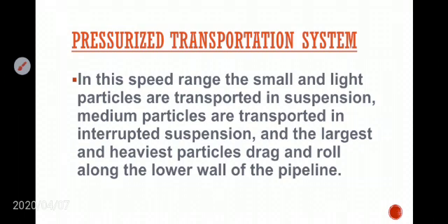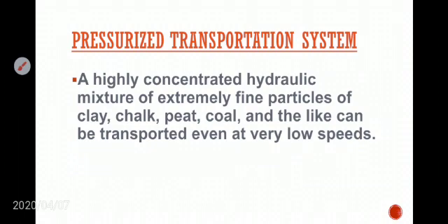And next, large or heaviest particles, that means the mineral pieces or ore pieces or material which is very heavy or large in size, will obviously get completely submerged in the water inside the pipeline, and they will definitely touch the lower wall of the pipeline, and will be dragged throughout the length of the pipeline up to the discharge end.